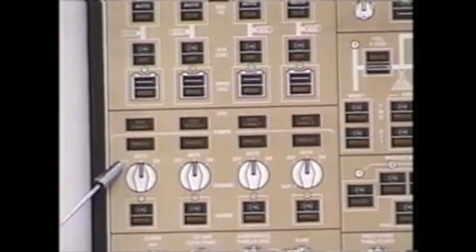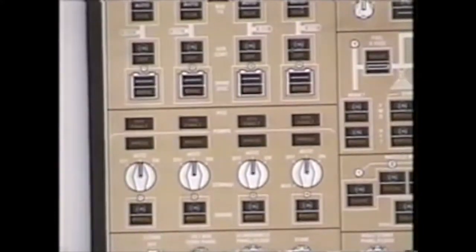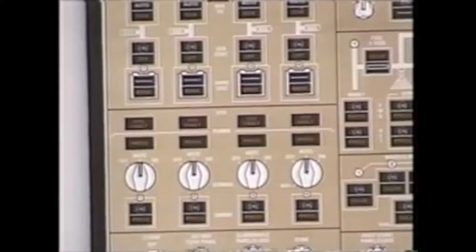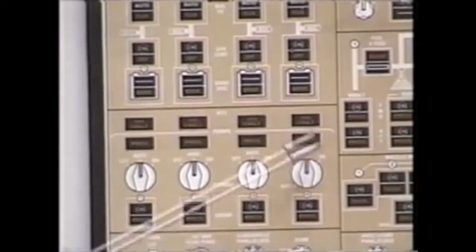With the ADP in the off position, the air demand pump is not allowed to run regardless of what's going on in your hydraulic system. With the ADP in the on position, that air demand pump will run continuously as long as it gets pneumatic air, again, regardless of what's going on in your hydraulic system. With the air demand pump switch in the auto position, there are 2 things which will activate the respective air demand pump in auto. Low system pressure, be it EDP failure or high demand, or taking the respective fuel lever to cut off, will automatically activate the respective air demand pump.